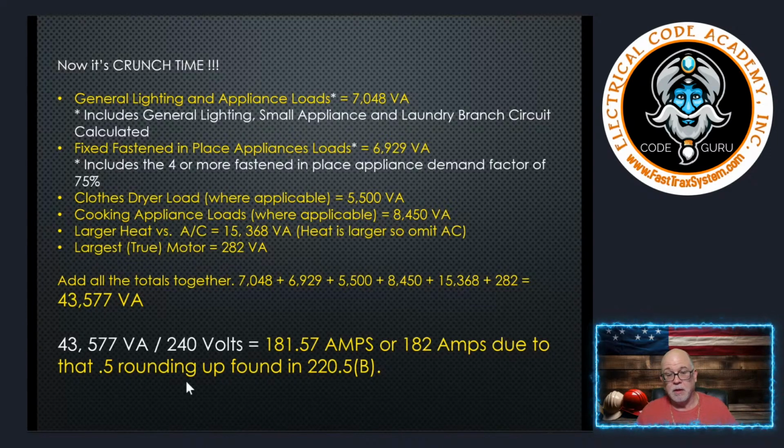Now, the first thing we need to do is size the overcurrent protective device. You and I both know that there is no overcurrent device that is 182 amps. Lucky for us, 240.4(B) of the NEC says that if it's not over 800 amps, and we're not supplying a branch circuit, which we're not, we're doing a load calc, and a breaker or a fuse doesn't correspond, then we can go up to the next standard size. We still have to size a conductor to handle the load, which is 182, but we are allowed to go up to the next standard size.